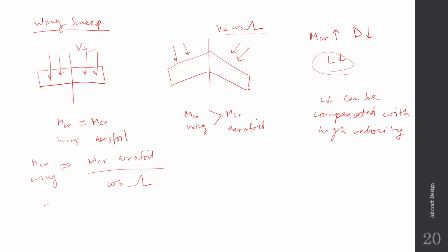Another small application, not a very important kind of application, but another small application of the sweep angle is if you have a tail heavy aircraft, or if you have an aircraft where the propeller or engine is at the back, okay, then you might have to sweep the wings to push the aerodynamic center backer.